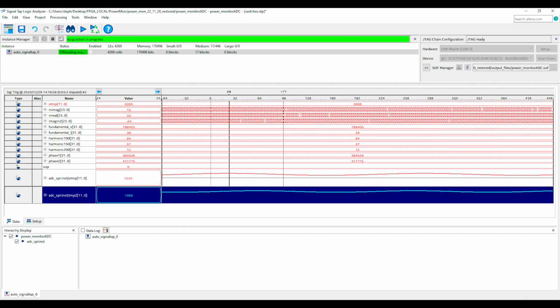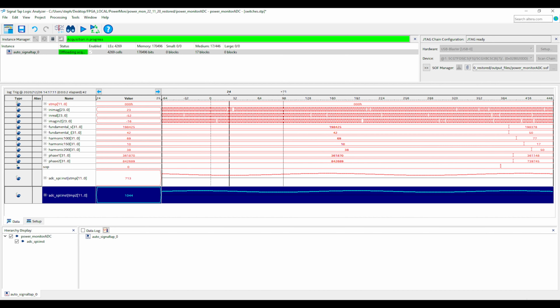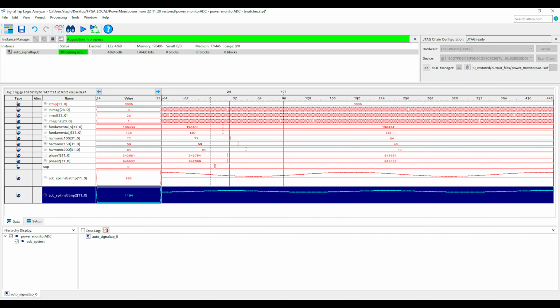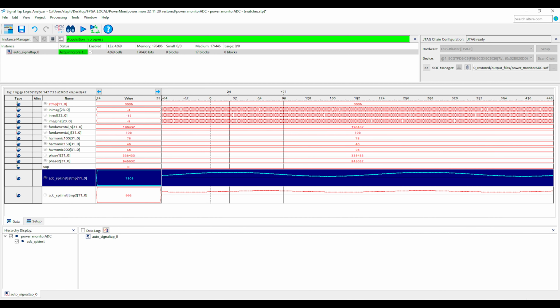And you can see that the sample depth I'm using here is 512 samples. I could probably do with going a bit larger than that to see more of the waveform, but this is 50 Hertz. And what I'm going to do now is, for one of the channels, increase the amplitude, and we can see if that has an impact. So that's this one. So these two are the 2 input waveforms.